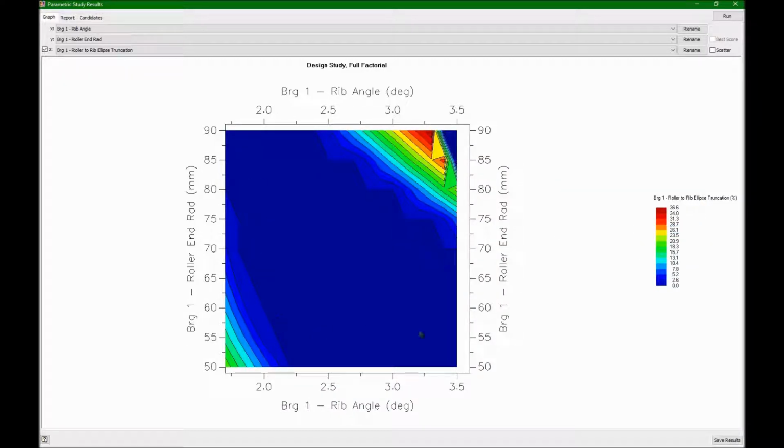So you have quite a nice blue area that I can deal with. And looks like I can go from 50 to 70. All right, that's pretty good. And I can go over as far as, now that's 2.25, so if I went down to 2.3 and to 3.5. So that gives me a decent manufacturable range. So what I'm going to use is the nominal of that. So about, it'd be 2.9 and 60. So that's right about in the middle, 2.9 and 60 is right here, roughly.